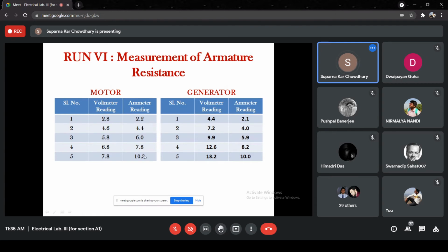This is what happens. It is a contact between the carbon and the copper of the commutator. Now this contact can never be perfectly flat. There are basically point contacts, because those two surfaces are not perfectly smooth, and it is not a perfectly flat contact between the brush and the commutator.